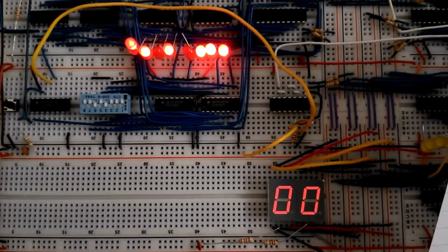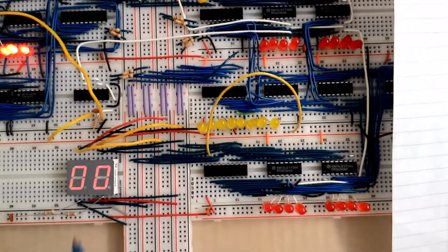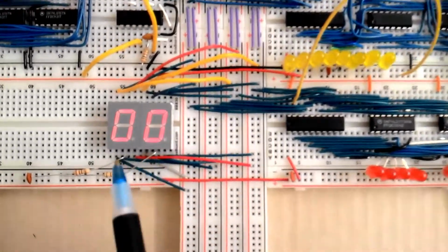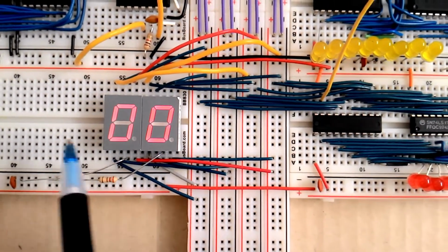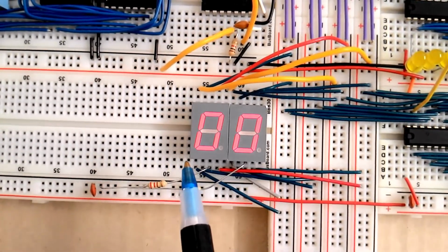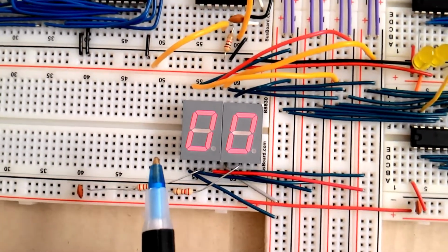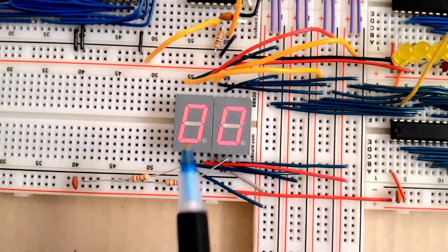We can see that this binary value is over here in our dip switches, and that is in our RAM, which is now going through the bus. So that is now coming to our data bus, and from the bus we read that value to our 7-segment display. Now we are going to have multiple displays, and we are trying to do multiplexing with these displays, and we will only see one value at a time.